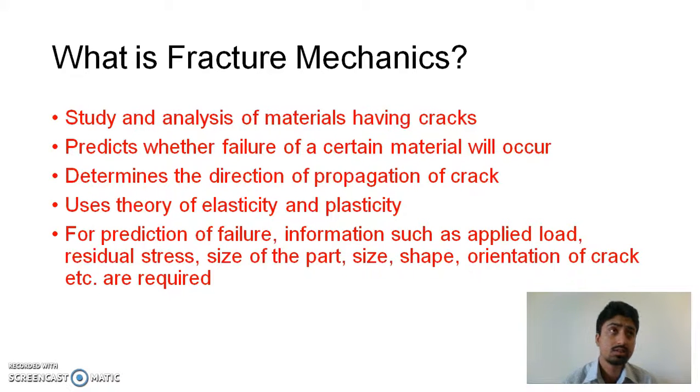So as I told, what is fracture mechanics? Fracture mechanics is the study and analysis of materials which have cracks. Using fracture mechanics, we can determine whether a material will fail. We can determine the direction of propagation of the crack. Also, we can determine other parameters like residual stresses due to the formation of the crack, and the shape, size, orientation and coordinates of the crack. Fracture mechanics uses the theory of elasticity and plasticity.